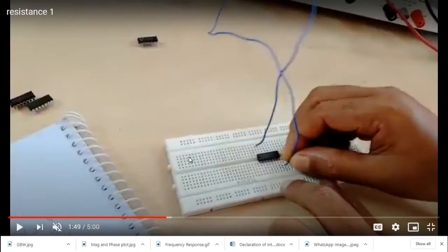Breadboard connection, segment number 2 and segment number 3: all the 4 dots vertically are connected at the same potential, meaning each vertical grid will be at a different potential. The 7408 AND gate should also be connected like that, with all the pins at different potentials. Hence we are utilizing segment number 2 and segment number 3.